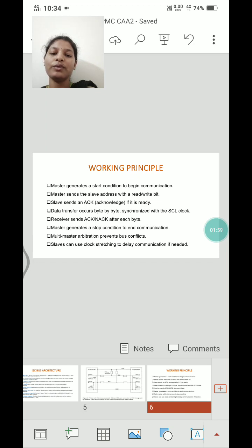Next, we can go through the working principle. Master generates a start condition to begin communication. Master sends the slave address with a read or write bit. Slave sends an acknowledgement if it is ready.